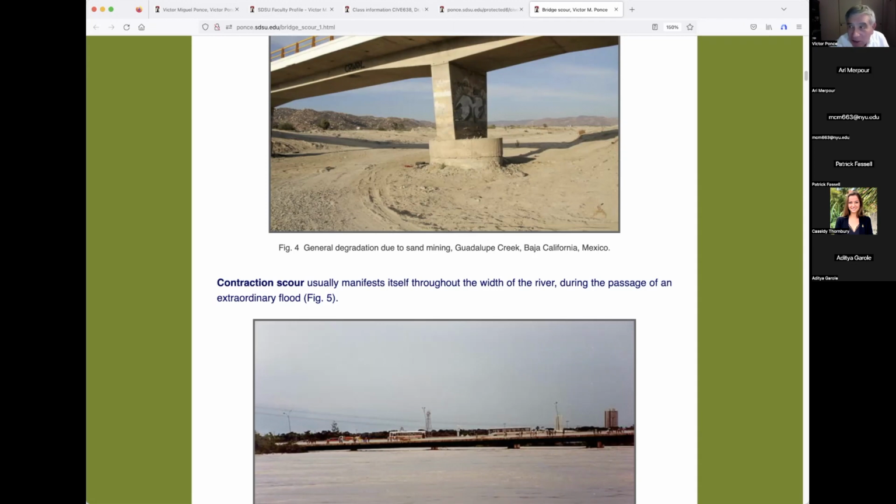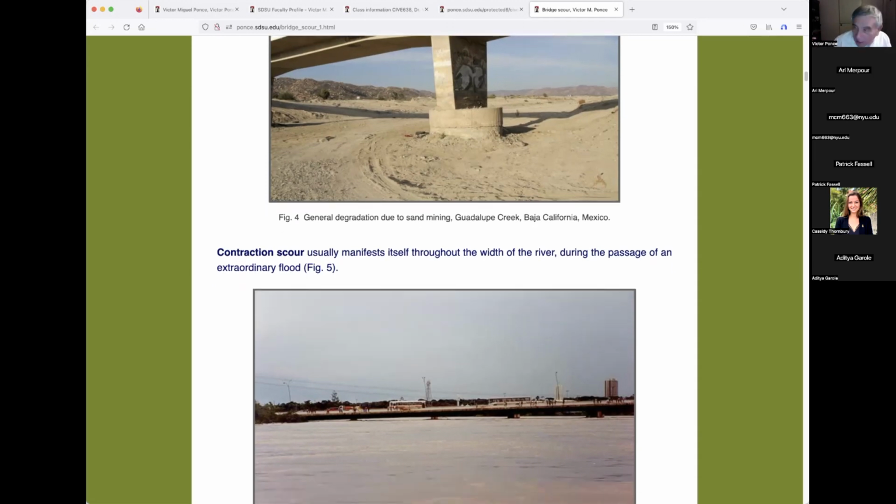They figured out, because of that, there's a report on it, by the way. It's a geotech report, so that's why I didn't include it in here. The factor of safety was 1.3, and during the failure it had come down to 1, and when the factor of safety comes down to 1, the thing tips over, right? That's exactly what happened. Why is it that the Army Corps was designing these structures with such little factor of safety? That's another issue that needs to be answered. It's a small factor of safety, 1.3.